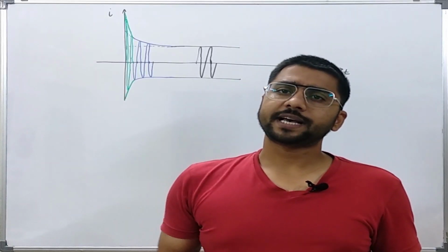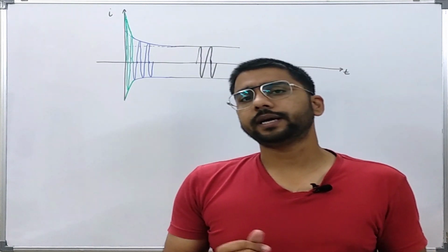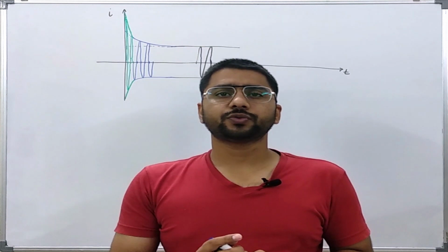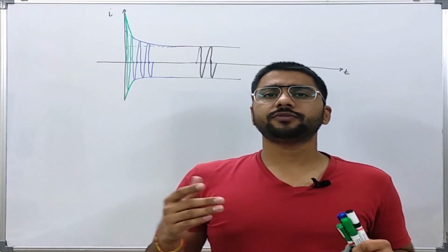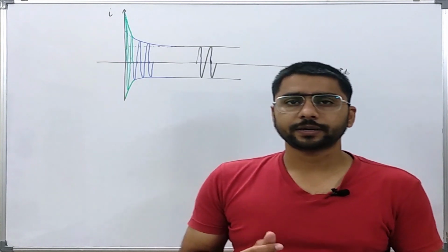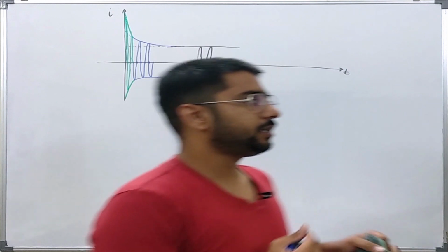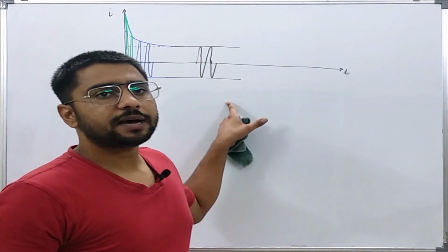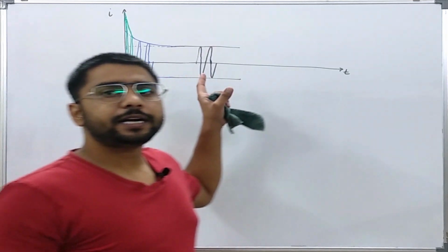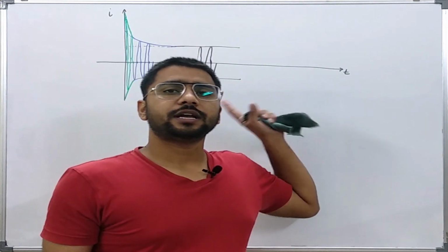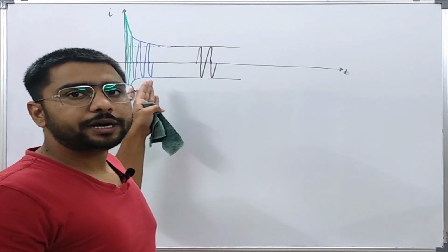One of the best ways to see the effect of a short circuit on a synchronous generator is to study the oscillogram of the currents on the various phases of the synchronous generator. Here in the figure I have shown a sample of an oscillogram which we will obtain if the DC decaying part, that is the natural response, is eliminated or not included.